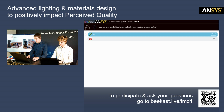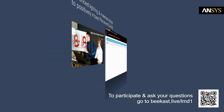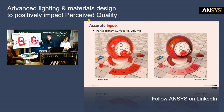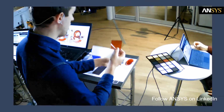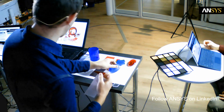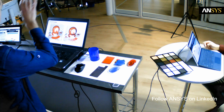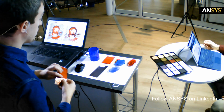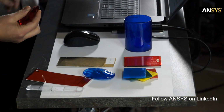Okay, let's move on to a different kind of material. Let's talk about transparent material. So in most rendering software, transparency is just a color applied on fully transparent objects. And that is physically represented by a surface tint. I mean, you take just a transparent sheet that you apply on your geometry and follow the shape. That's what happens on the first sphere here, where you can see the red transparency is homogeneous all along. But for transparent objects, generally what we have is a volume tint.